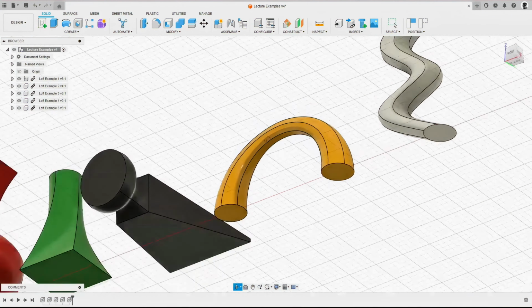We're going to select this top face here. And in terms of thickness, let's go for 2 mil. See how that comes out. Press OK. Yeah, it's looking nice. We've got our unique looking vase there. So let's see how we can edit some of these faces then.